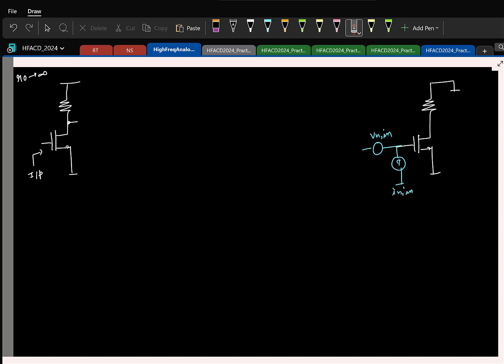And to find the noise voltage, what should I do to the input side? Rs is 0, so which means I'll go and short it. So let me actually keep the circuit here and short it. It's all small signal, so incremental circuit is what I'll draw quickly. So input is shorted. Here also it's shorted. Let me demarcate these two.